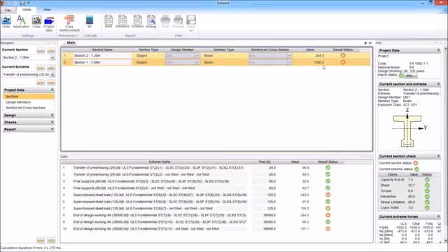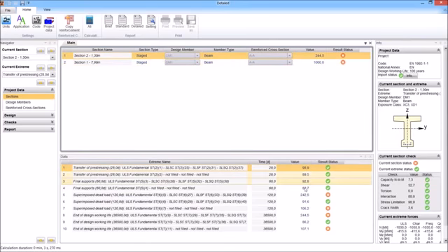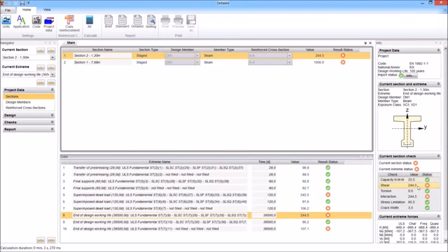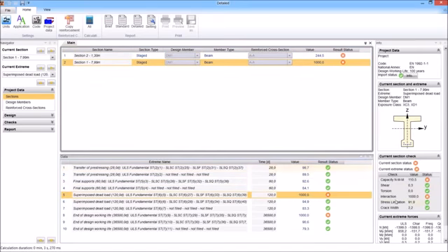So we can immediately start calculations, and the program ran these two sections in all these extremes. You see that in the first section above the support we have unsatisfactory shear because there are no stirrups. In the second section we have unsatisfactory even the capacity, about 10% more, and as we check also the interaction of all internal forces, and the interaction calculation is based on the response of the section, the response was not found because of insufficient capacity.